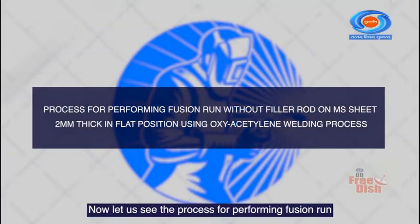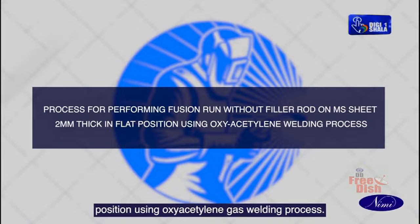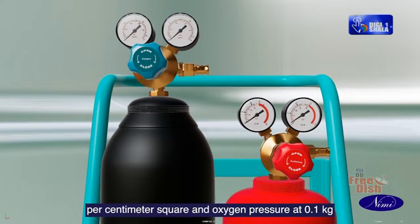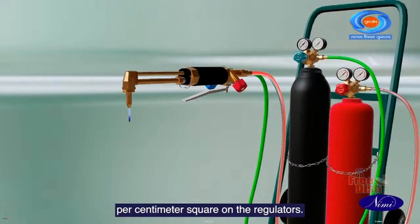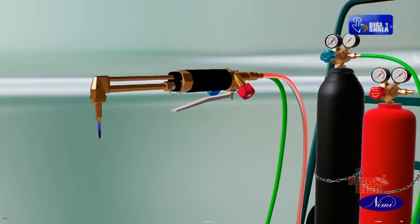Now let us see the process for performing fusion run without filler rod on MS sheet 2 mm thick in flat position using oxy-acetylene gas welding process. Set acetylene pressure at 1 kg per centimeter square and oxygen pressure at 0.1 kg per centimeter square on the regulators. Ignite the oxy-acetylene gases and adjust the neutral flame.